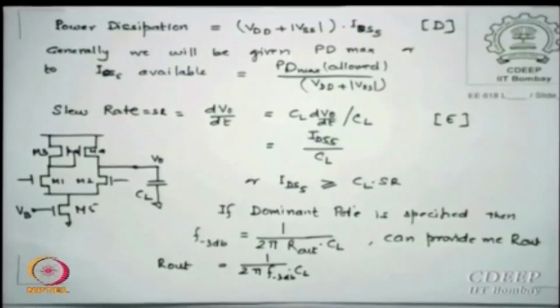I say, okay, how much heat sink am I providing for the chip? That is called the thermal resistance available to the ambient from the source of heat. So I solve a thermal conductivity equation, continuity equation, and figure out, for given thermal time constants, that is the conductivity of the materials I am going to have in series, how much heat I can dissipate so that temperature does not exceed this. Delta T by delta P is called thermal resistance.